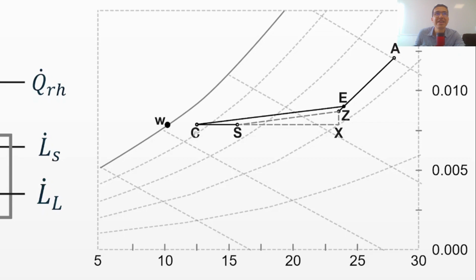The conditions of the coil are kept fixed to take care of the latent load, and these temperatures are typically between 10 and 13 degrees Celsius to meet the latent load. These choices ensure that the supply can control temperature without allowing humidity to drift high. We have to control the humidity.